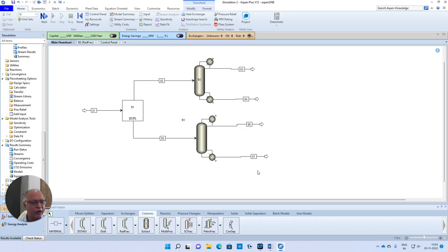Maybe vary any other variable which is going to have an effect on the purity of the bottom product. For example, distillate rate. Remember, reflux ratio and distillate rate may be dependent on each other. Now, when you put these two variables as vary, the simulator has to find a convenient result which is going to satisfy both the requirements. Normally, you should be able to do this.